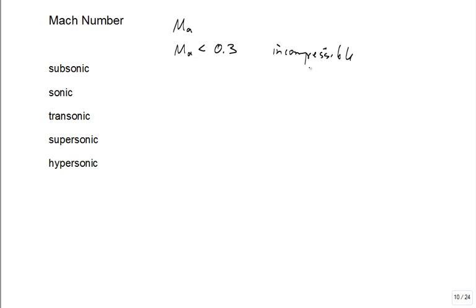Professor, if we heat it up, doesn't the density change? Yeah, but not due to pressure effects. A lot of times when you study HVAC, heating, ventilation, air conditioning systems, you're heating up the air and you're cooling it down. The density is changing, but the pressure change is so small. You're not changing the density because of increase and decrease in pressure. It's because of increase and decrease of temperature.